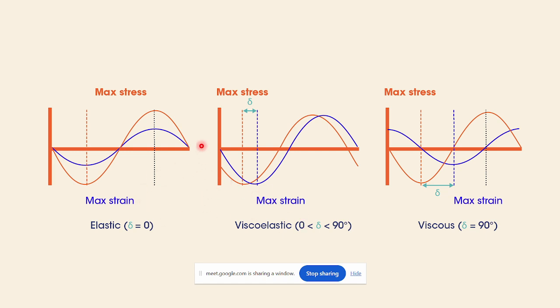If there is a very high amount of filler, you will see the elongation at break will not be very high, because fracture will happen, and also in between the filler there is what is called the Payne effect. Because of that, ultimately your material will break down.